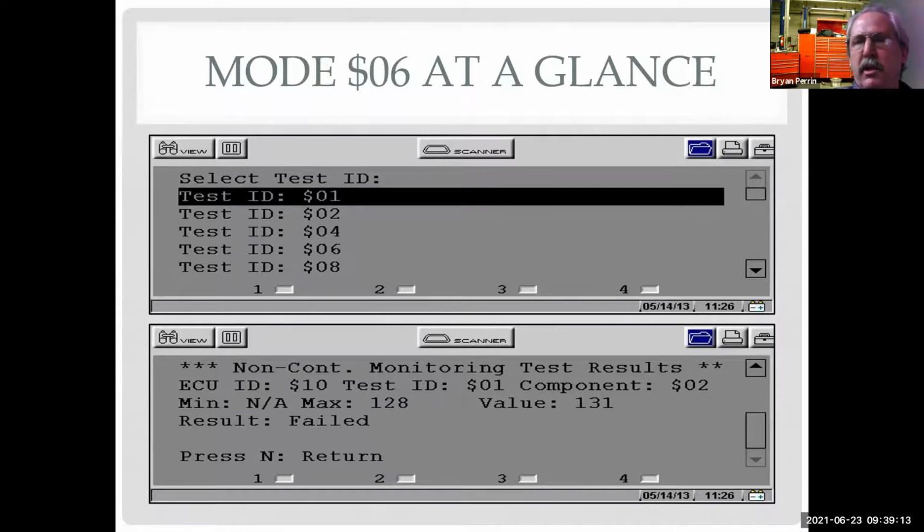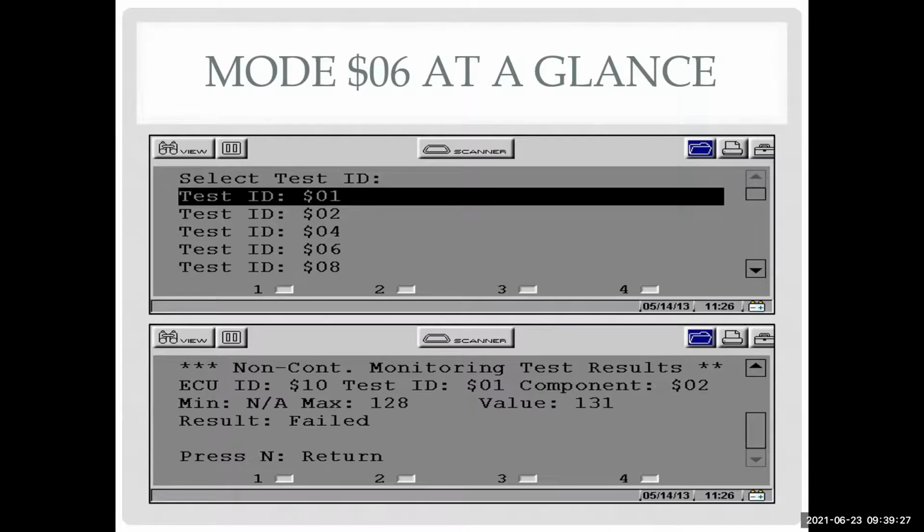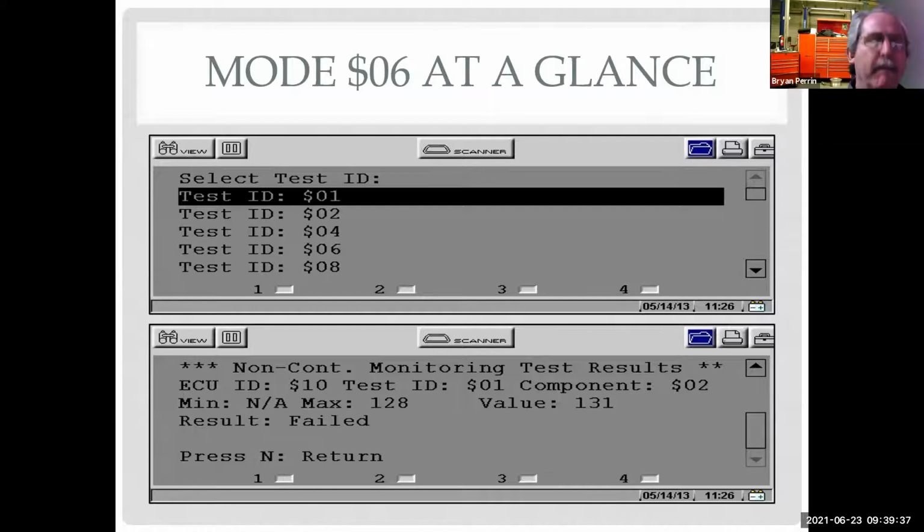So normally, you'd want to treat a P0421 the same way you treat a P0420. They're both saying the bank 1 converter that is being monitored is not working at correct efficiency. And that could be because, I don't know, it's clogged or saturated with something like carbon.